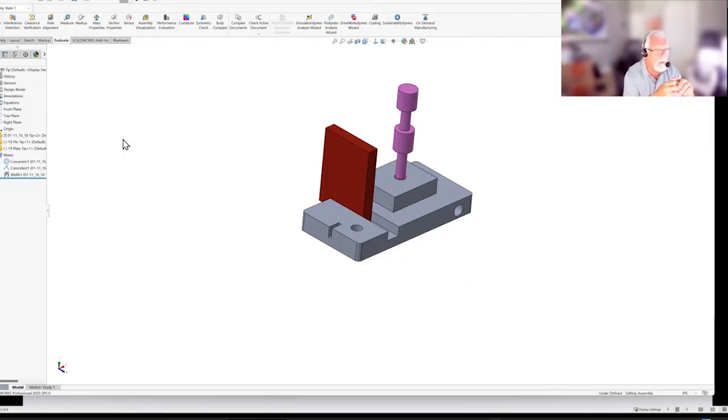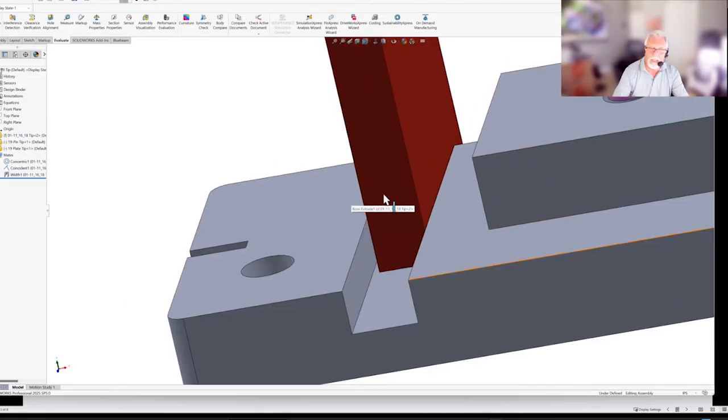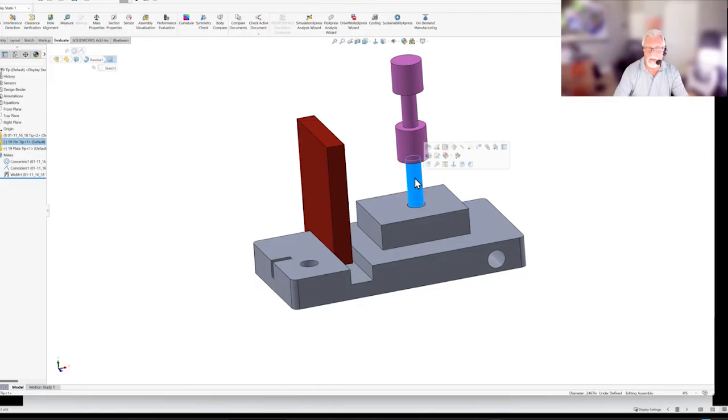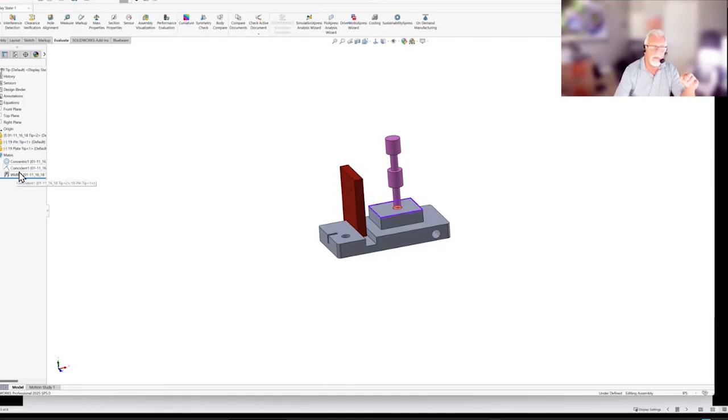Just a question on that, especially on the assembly thing, centering the part and stuff like that. I'd be curious how many people were aware of that, or of what we did here, hitting that Alt key as you drag it, selecting the feature. If I would have selected here instead of the edge, when you select an edge, it's looking for the similar edge and diameter, and that's why we got the 2. But if I selected here, it would have selected just the diameter to insert in there. So hitting that Alt key when you're dragging your part around is really, really helpful.